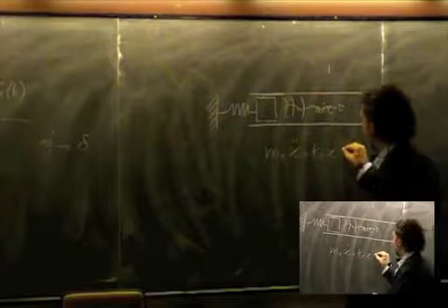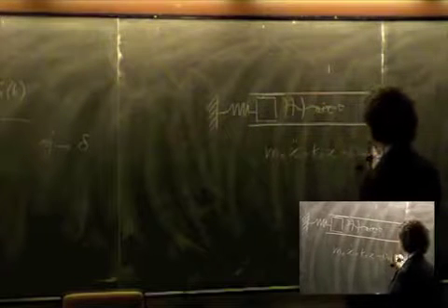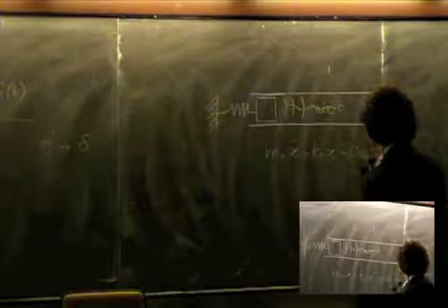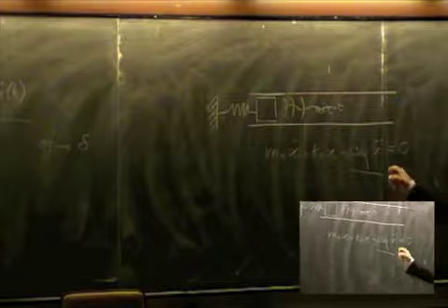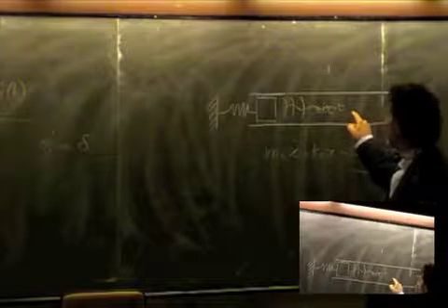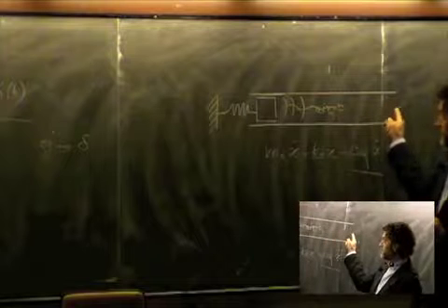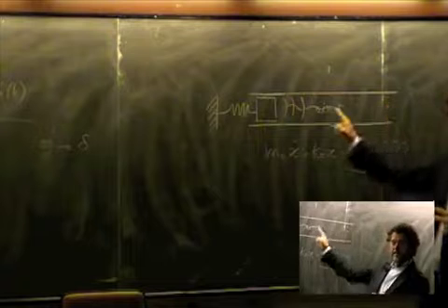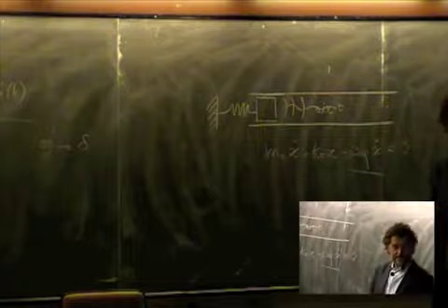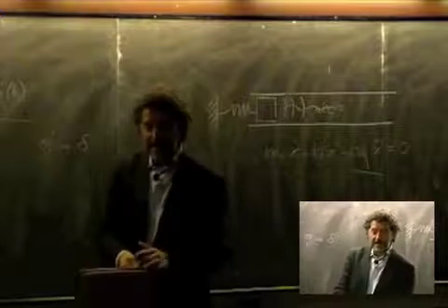So if you make the calculation of this very simple system, you will find that it behaves exactly in this way, in which you have an equivalent damping that is just expressed in terms of the stiffness of the material that is contained in the waveguide, the section, and the speed of the waves along the pipe. So three parameters that have nothing to do with real dissipation mechanisms.